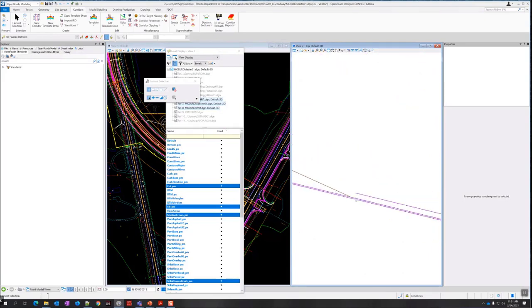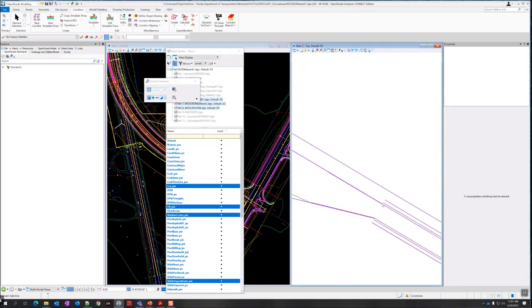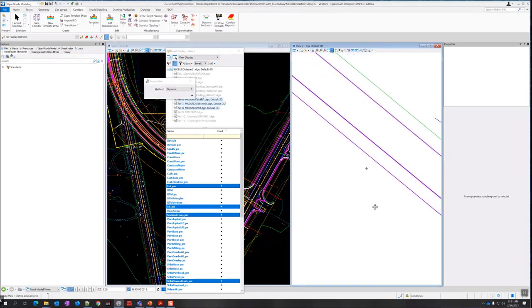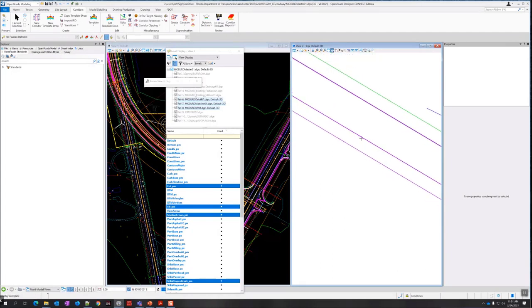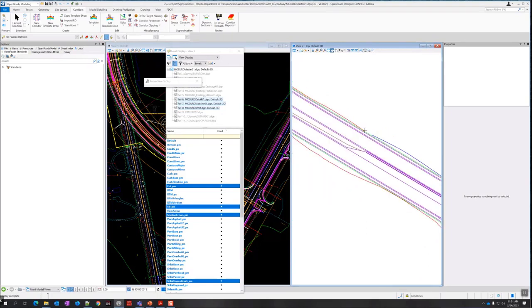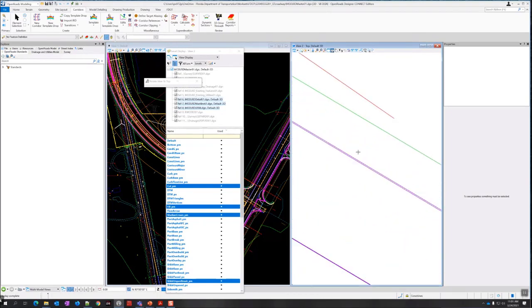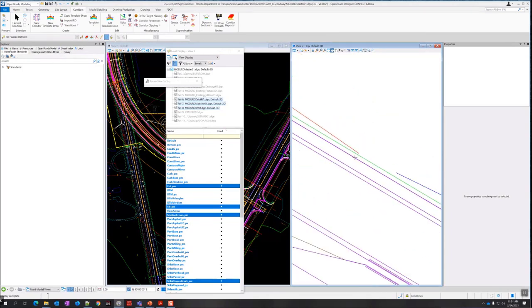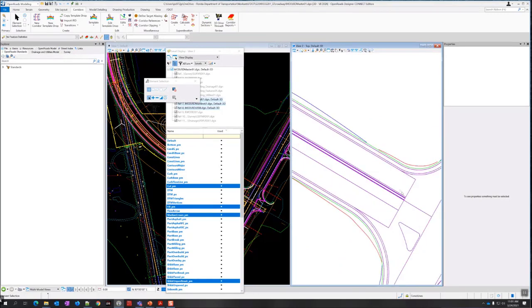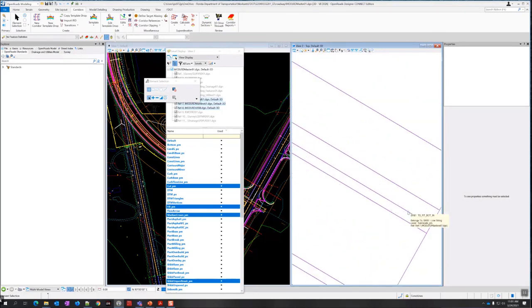Again, close to each other is fine. On top of each other is not fine. So these are fine because they're close to each other. And it's hard to see if it's on top unless you do rotate. Say, look, oh, there's 3 lines stacked there. Is that a problem? No, it's not. When you zoom in, see they're right next to each other. So not a problem. That's just my back of curb sidewalk lines where things are changing elevation. But yeah, this traffic separator one looks to me like it's going to be an issue.